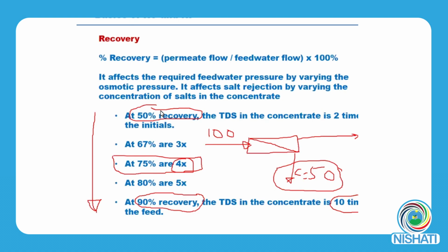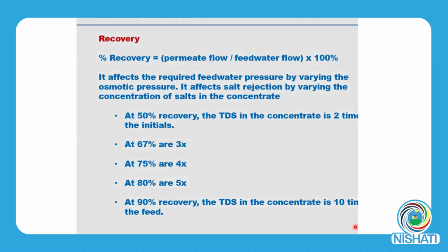For instance, for seawater, it's not possible to increase beyond 50% recovery because some salts can precipitate and the energy that you need to apply and the resistance of the membranes can be overcome. So it's not a good idea in seawater to go beyond that recovery. However, for brackish water, you can increase the recovery, but depending on the sparingly soluble salts, okay?